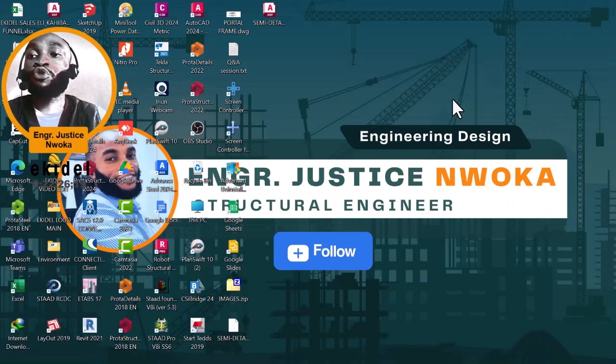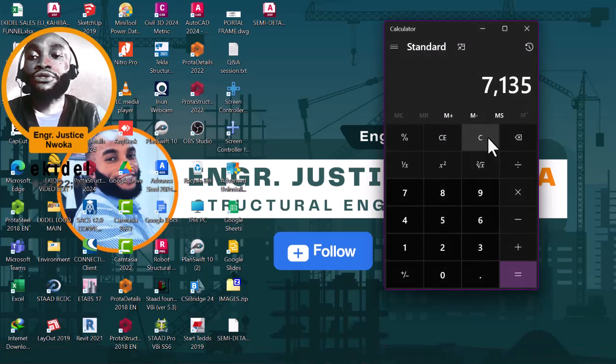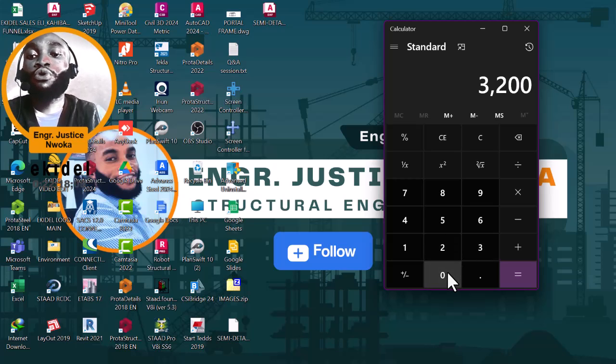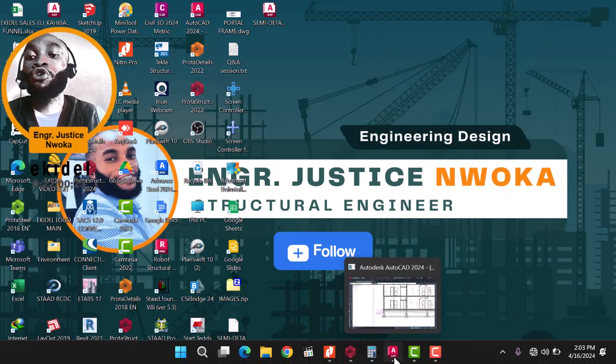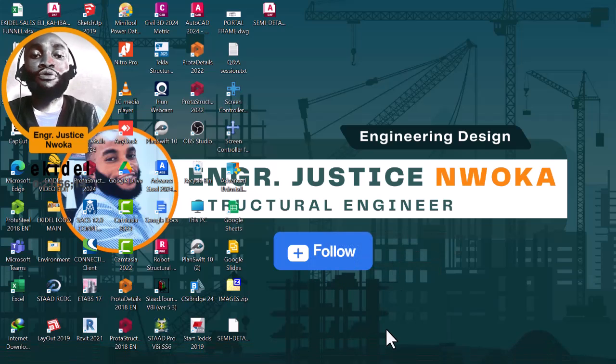Okay, with that, let's check that in the calculator. We have 3200 as the story height minus the roof beam depth of 300. 3200 minus 300 gives us 2.9 meters as the height the block wall will occupy.